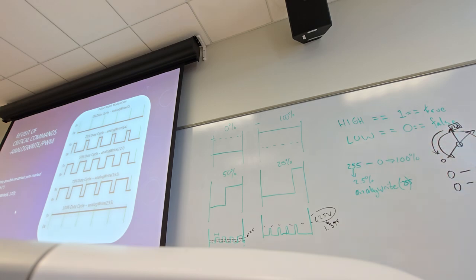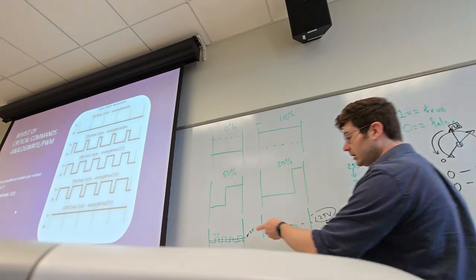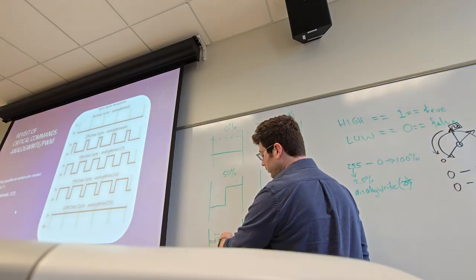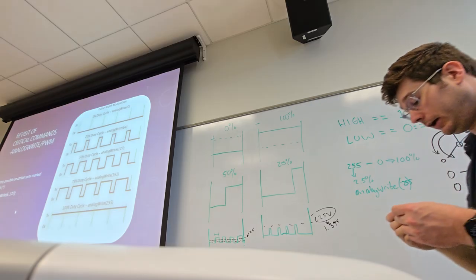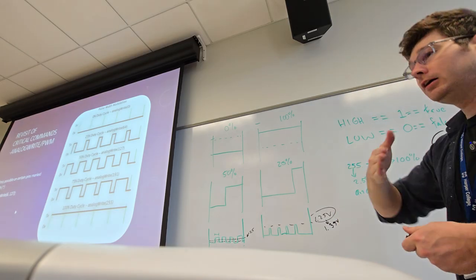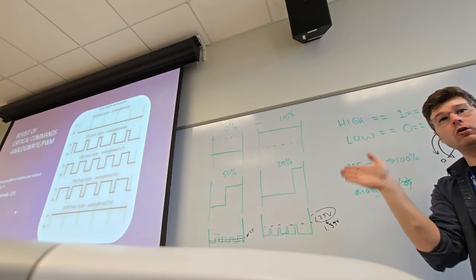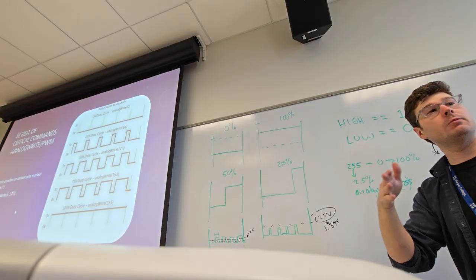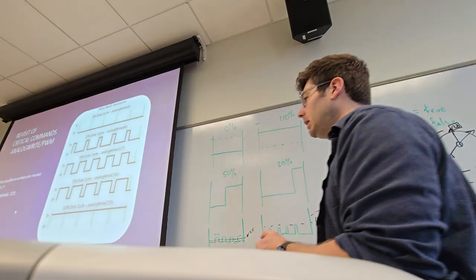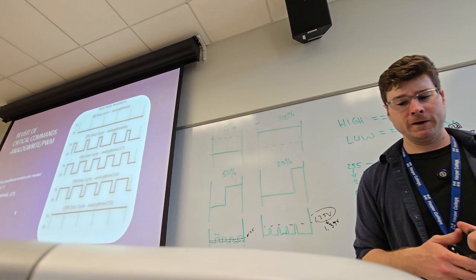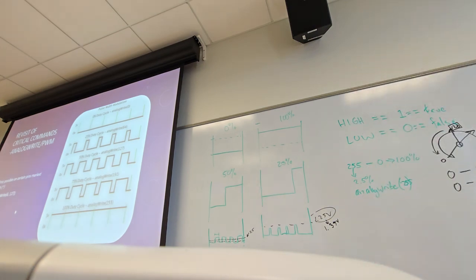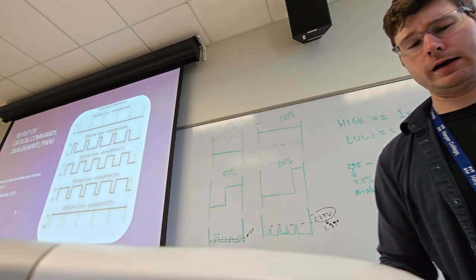What the servo is literally getting is this weird sawtooth signal, but it knows how to decode that. Based on the width of the signal, it knows the position to go to, kind of like a lookup. And it's not the only device that can do that. There are also proportional valves that can be more opened or more closed depending on the PWM signal they get. It's very common. Motor speed controllers have that as well. It's just another way that we can interact with our world with granularity. Speed controllers work with that a lot.